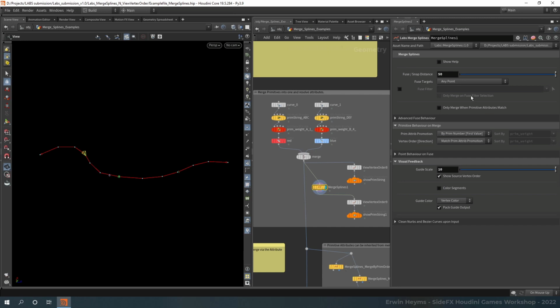So in this case, I have snapped it using a snapping value up here. If I lower this, notice how the curves don't snap. And if I increase the value, you'll notice how the curves will start merging. Now, if I set the value too high, the curves will start snapping to themselves, and then you won't get a good result. So if you want to, you can also specify that it should only snap the endpoints, or any endpoints and intersections. So that, even if our snapping value is very high, it will still merge the curve into one.